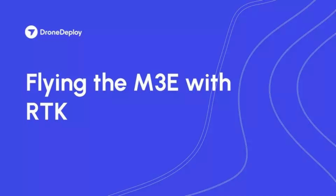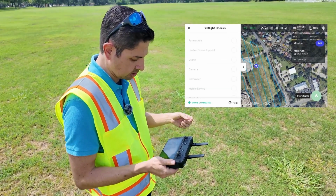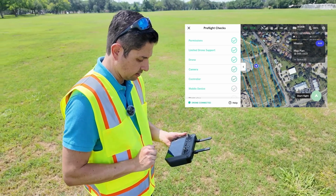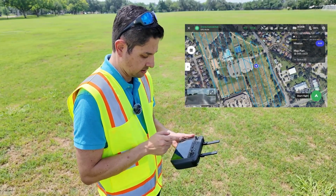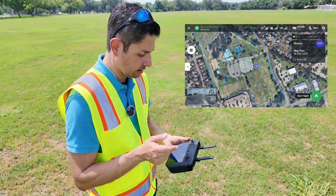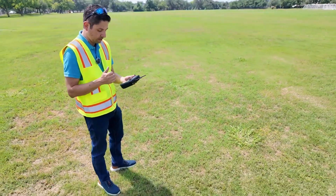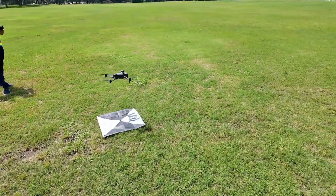All right, as we're getting ready to start our flight, checking our altitude and everything, we're satisfied, airspace is good, RTK coverage is green. I can start my pre-flight checklist. Submit it. Here is a good idea, again, to check that RTK flag. If it's amber, it's still going to give you an alarm, and you can retry that connection and then make sure that it gets to the green. Once that flag is green, you're good to go. You should be getting corrections for the flight. We're going to click start flight and check our drone.